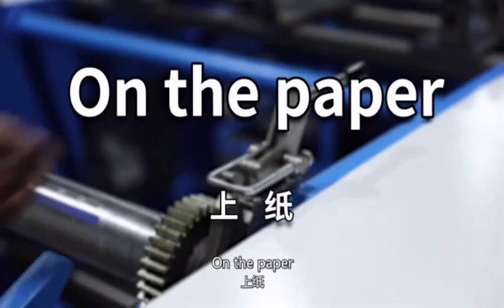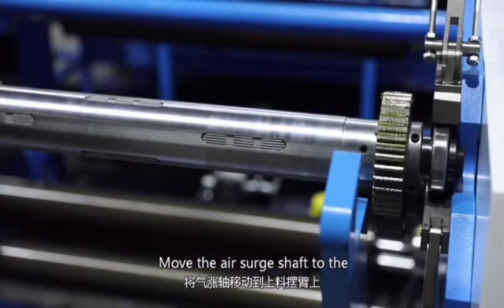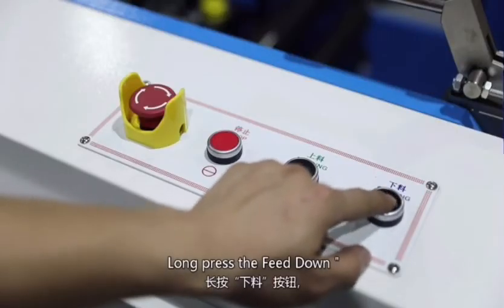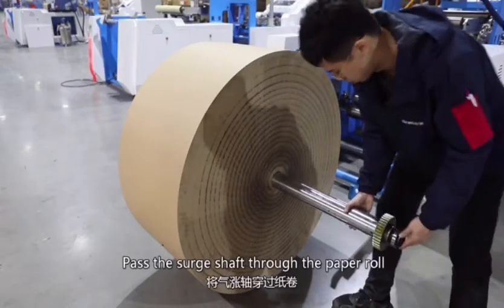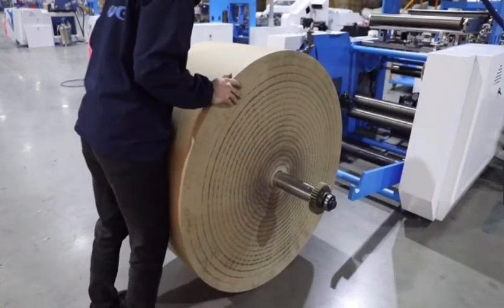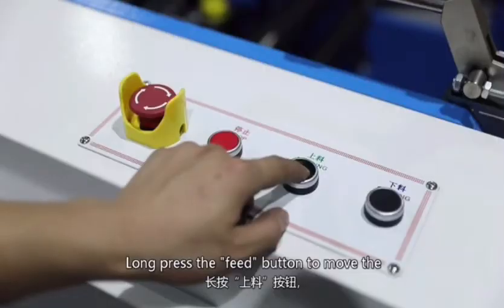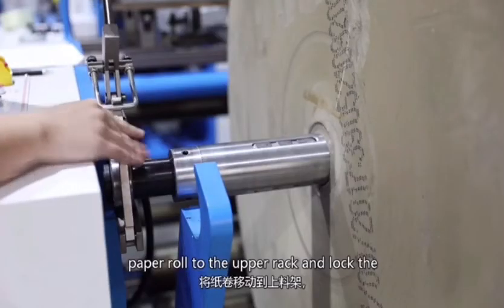On the paper, open the air surge shaft buckle. Move the air surge shaft to the upper material swing arm. Long press the feed down button and drop the air surge shaft. Pass the surge shaft through the paper roll. Long press the feed button to move the paper roll to the upper rack and lock the buckle on both sides.